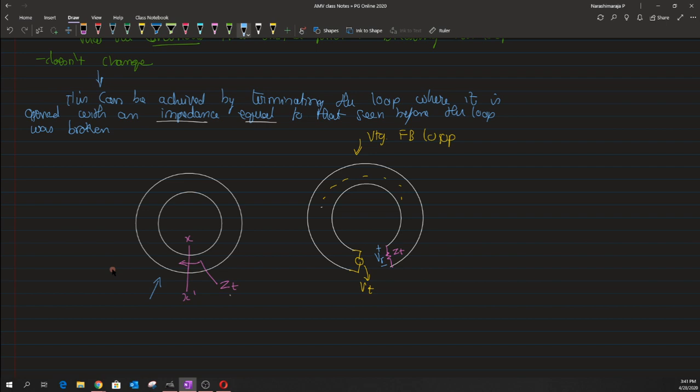Okay, and the ratio of Vr divided by Vt would give us the value of this loop gain, which is A beta. It always has to have this negative sign just because the feedback that we had was a kind of negative feedback. So the negative ratio of Vr by Vt will give us this loop gain. Okay, this is what we theoretically want to know.